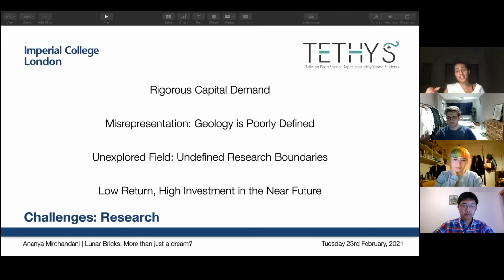produce different results. With respect to compressive strength too, for example, the ISRU brick apparently had 10-fold compressive strength to conventional bricks, because it used something called guar gum, which is a bacteria that you find on Earth, whereas the Regolite brick was just 5 megapascals. And when you compare these two, you can't say that the ISRU brick is better because it's of course not independent of Earth resources, hence explaining why things are hard.